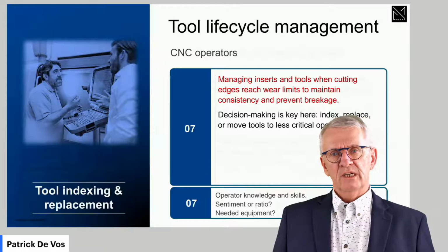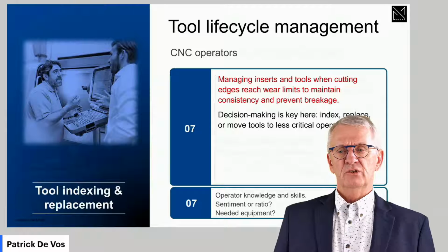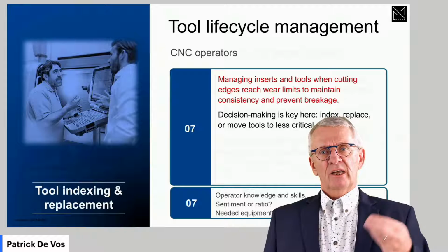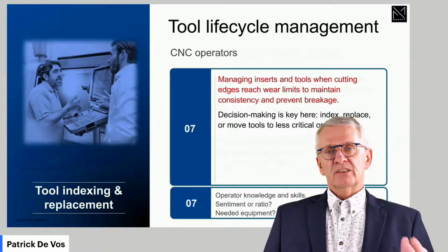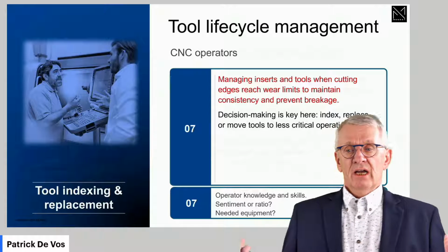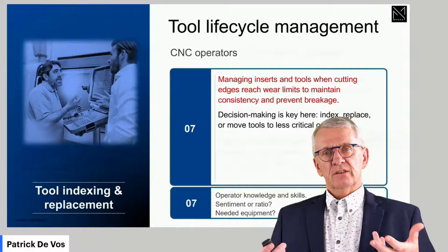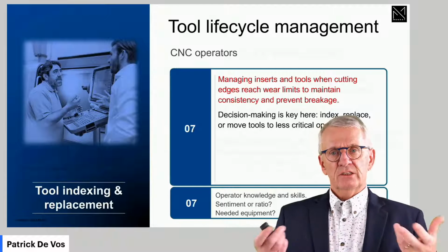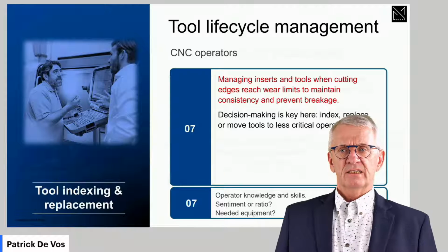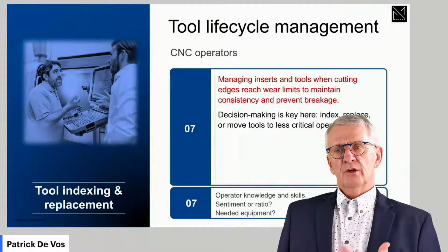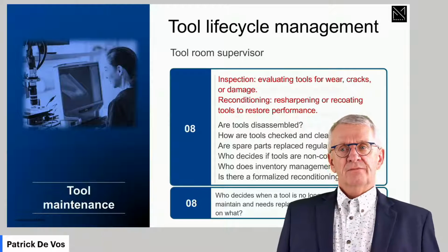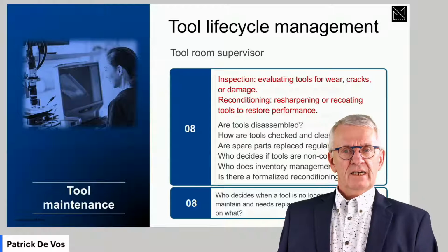After a while being used, there is somewhere that tools need to be indexed, cutting edges need to be indexed. Indexed means replaced because they are worn out. But as a certain tool can have more than one cutting edge, think of insert type tools, after a number of indexations, the collection of cutting edges, the inserts, needs to be replaced. So it's indexing, replacement. Again here, this is something for the operator. But an operator should be well instructed so he knows when to do it. After replacement, the tools go back to the tool room.